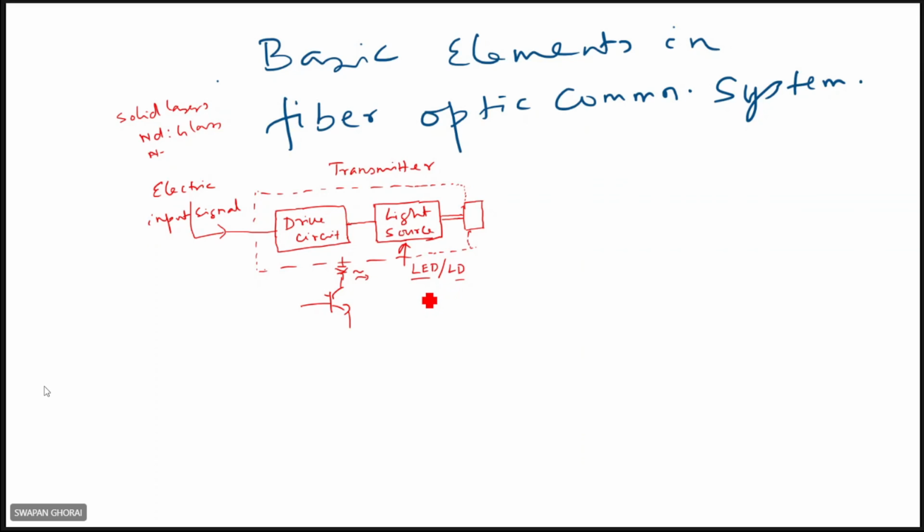The material should be of direct bandgap type, so that you can have high efficiency, high power, fast response times, right? And not only direct bandgap type, but they must also be of DH structure, double heterostructure based devices, these light source materials, right? And also there are different configurations. It cannot be a simple LED. It will be, say, double heterostructures,